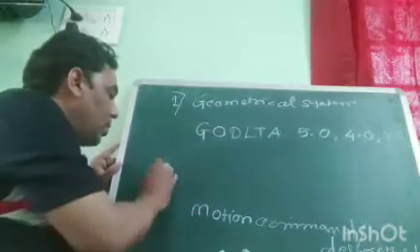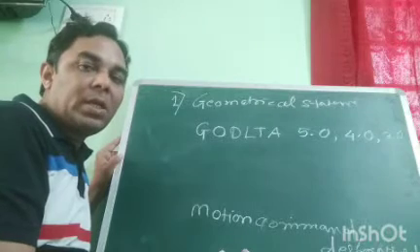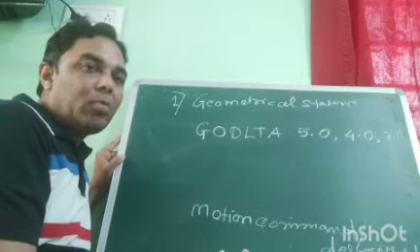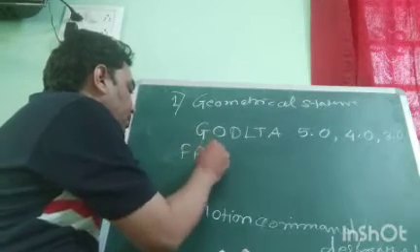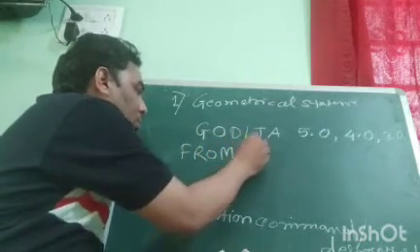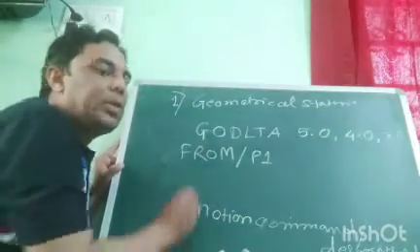Now see the different motion statements which are basically used in APT part programming. Most frequently, FROM/P1 means we start from P1, as we have seen previously.